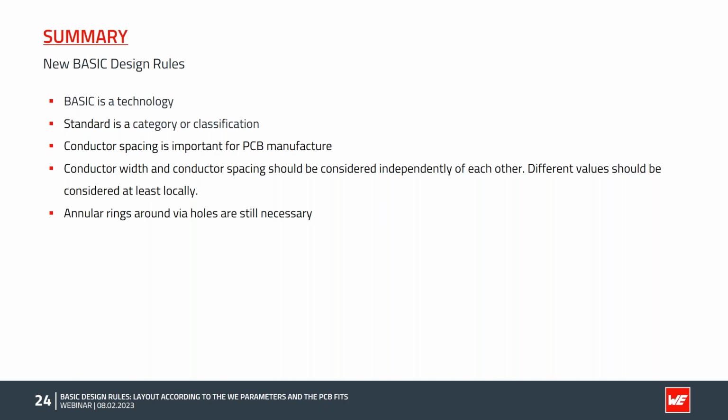Annular rings around wire holes are still necessary, and non-used or non-functional pad removal does not save space on inner layers, especially on ground planes. And last but not least,